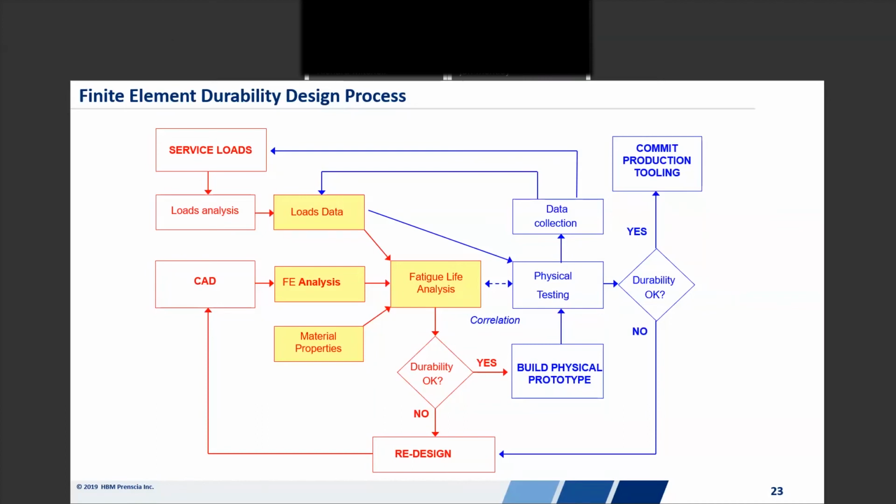I can then bring those into ANSYS Design Life, where I take the stresses from the FE, from the virtual model, and pair them up with measured or estimated load histories and put together stress histories just like we had as a starting point on the previous slide. From that, I can predict fatigue life for every component of my part, or every test location, node by node, element by element. In this virtual calculation, we can quantify whether we're going to hit the fatigue targets we expect with our design.